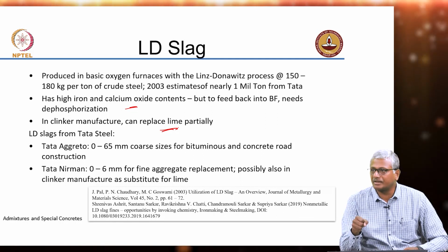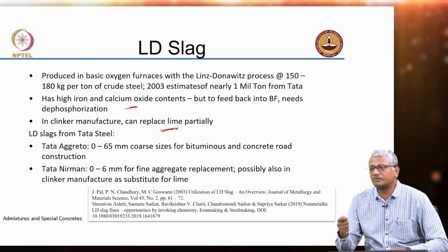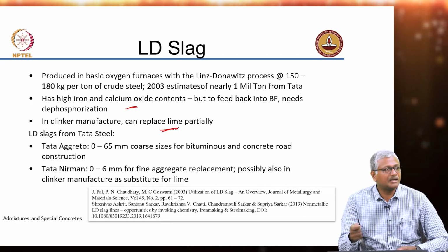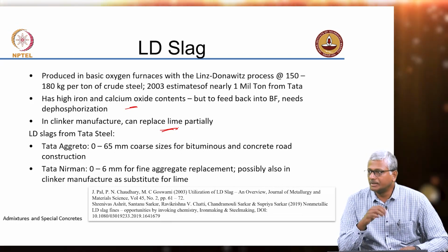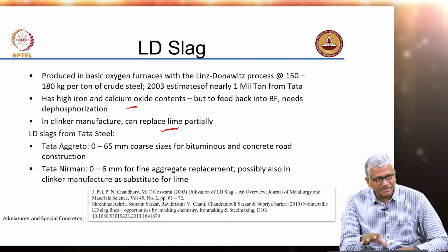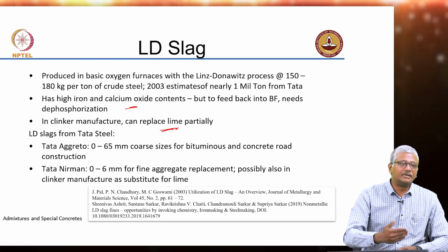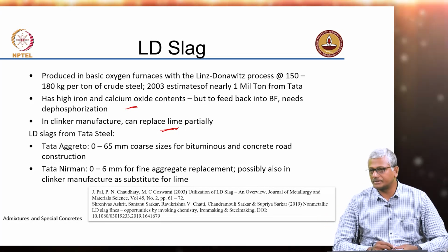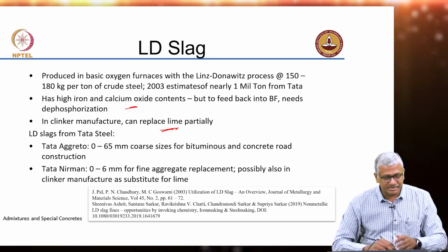So, you need to crush the aggregate, energy is involved, and you need to justify whether the energy you are putting in to make this aggregate is really giving you the kind of performance that you expect in new concrete. Okay. So, it is not just technical aspects that we need to look at from the performance perspective, the processing and production of the material are also equally important to consider. As engineers, we need to make decisions that consider all of these aspects together.